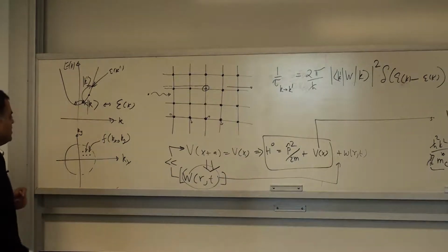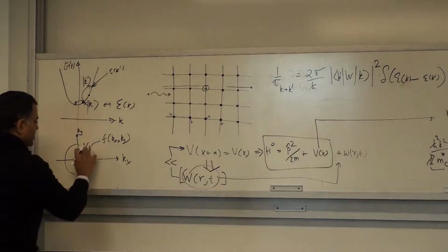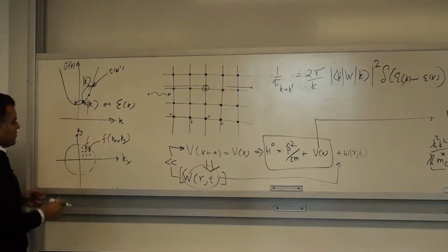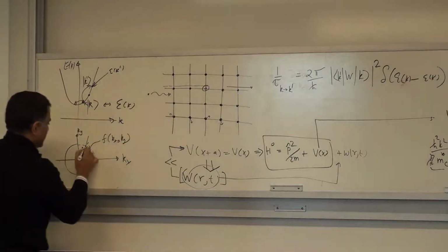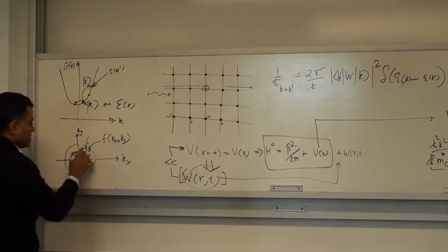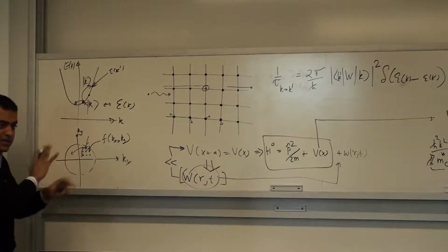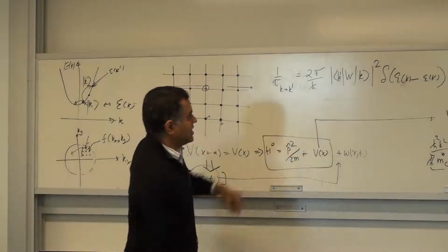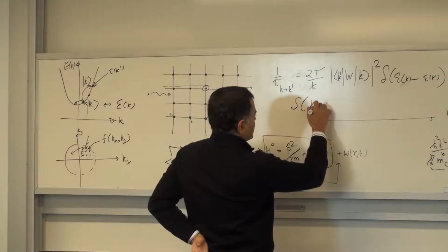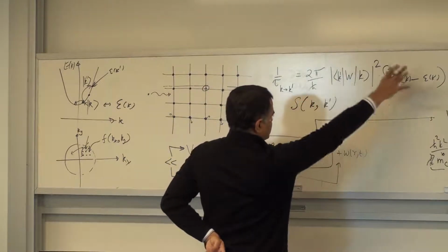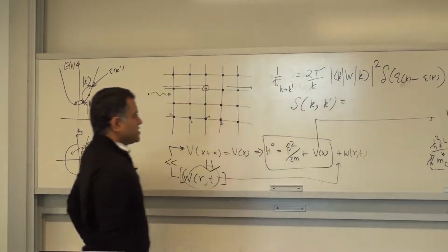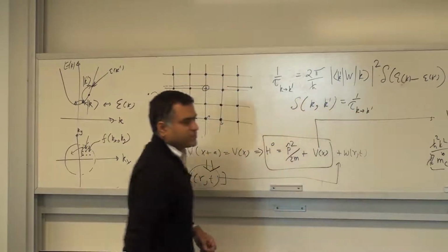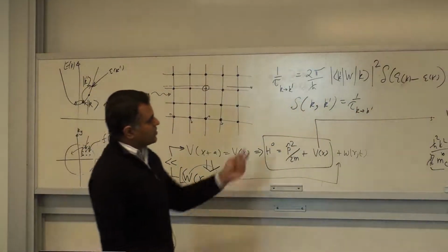There's no scattering allowed. But now what we are saying is that an electron that's going from the source to drain, maybe it's in this mode, because of these defects, these variations, it can scatter into another state, maybe here. It can scatter into another state there, and so on. We are allowing for mixing of the states now, right? So that is covered by this relation, and we are going to write this just as S k comma k prime, just trying to avoid writing the whole expression for now. 1 over tau from k to k prime. Yes, the scattering rate from k to k prime.